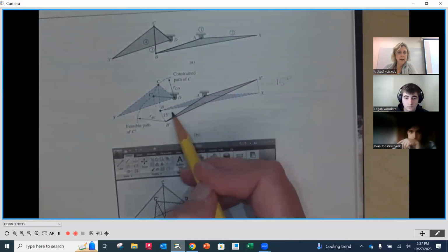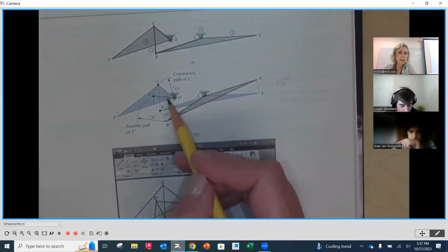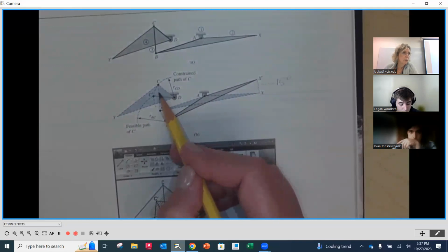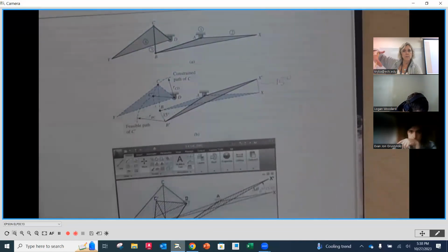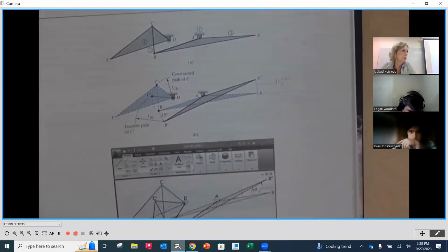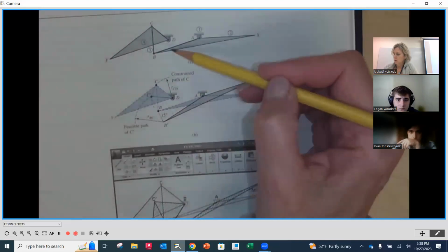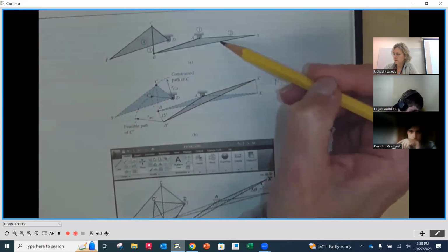So when it's open, what we want to do is reconnect back to that lower handle and rotate it to see what the angular displacement of that handle is, to find out if that's reasonable for how far you'd have to pull your fingers apart to get that to happen, right? As you look here, you'll notice that they marked off their path for each one of the points that's connected back to this link number 1, okay?